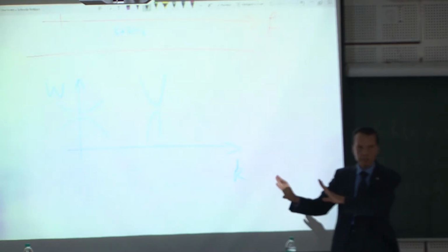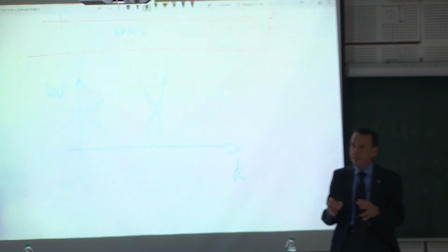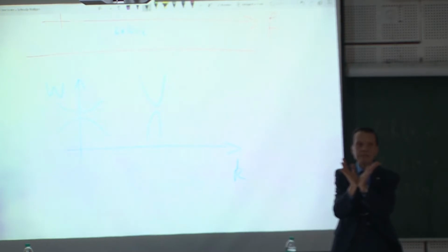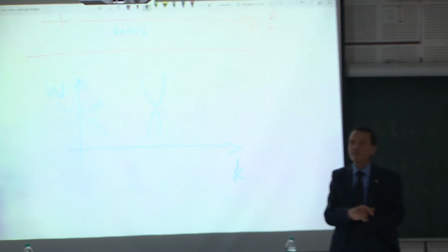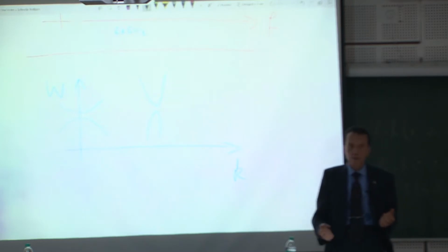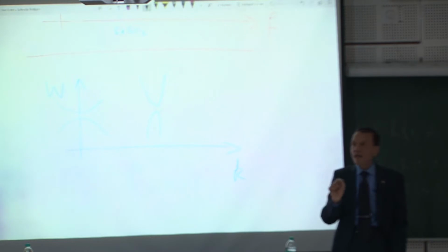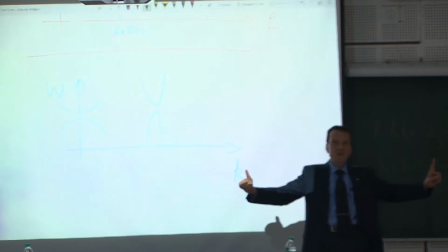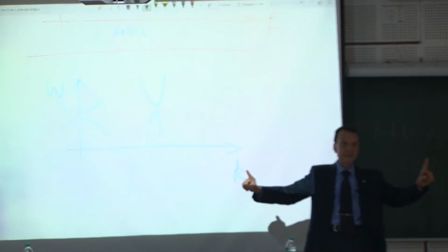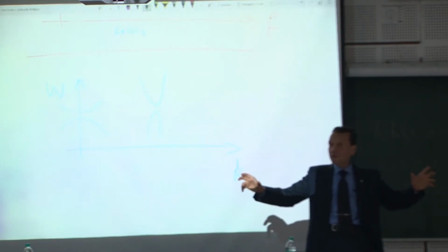This is actually semiconductor research, inventing a new material for which these energy gaps are as narrow as possible, because one over that is the effective mass, and lower effective mass means higher mobility. So in this case, my electron, my hole, is very, very fast, so that I can have a short transit time and at the same time keep the distance between the source and the drain big enough to avoid breakdown.